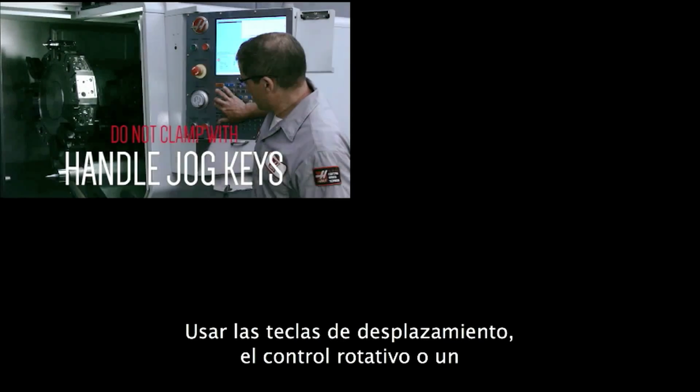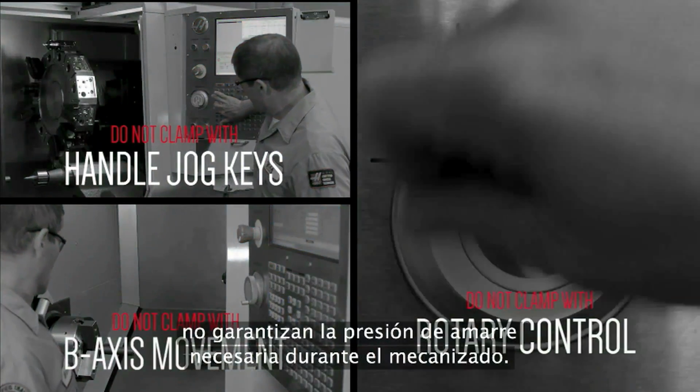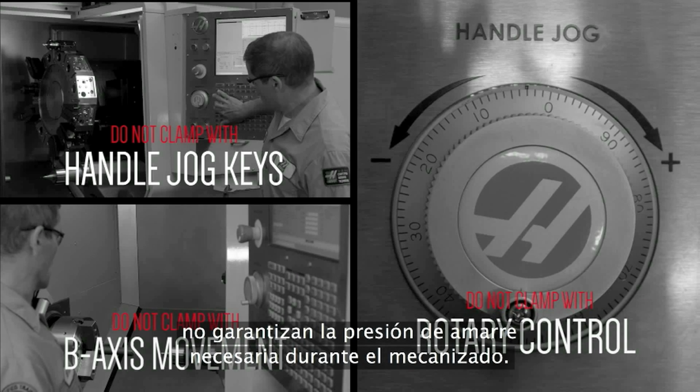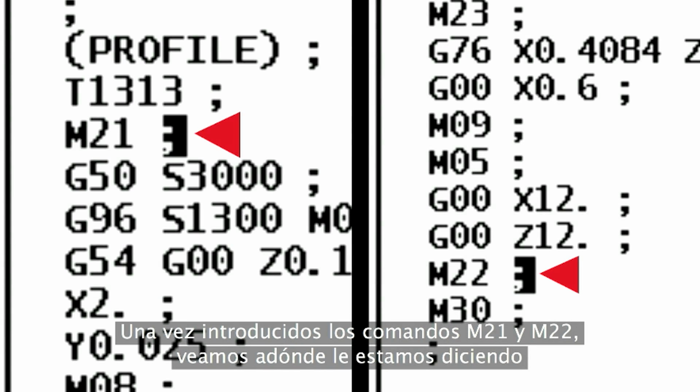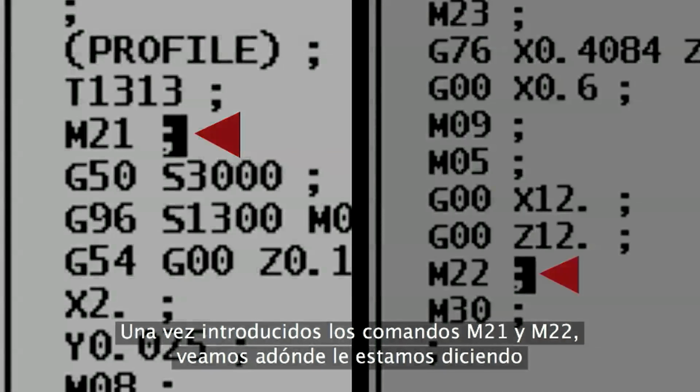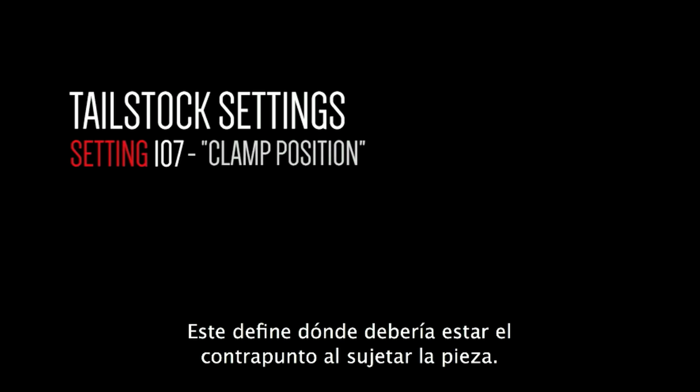Using the handle jog keys, the rotary control, or commanding a B-axis move will not maintain full clamping pressure during cutting. With our M21 and M22 commands in place, let's look at where we're telling the tailstock to go. We'll start with setting 107. This defines where the tailstock should be when it's clamping the part.